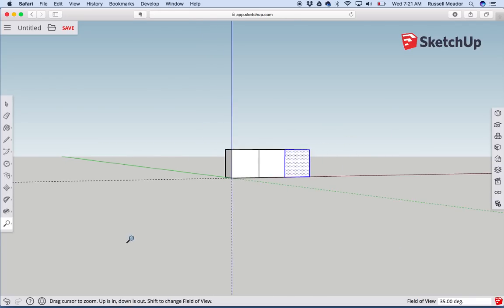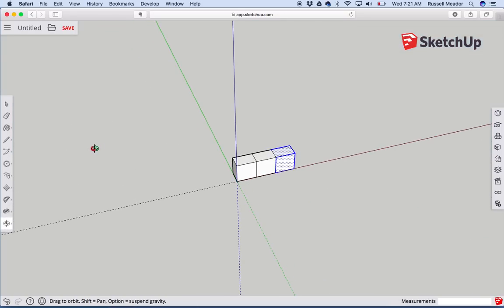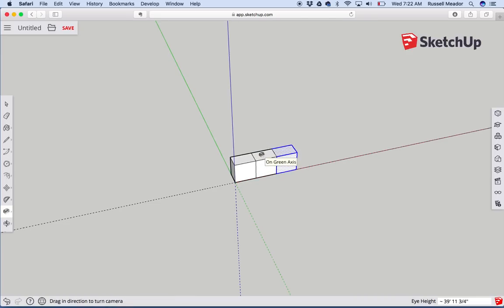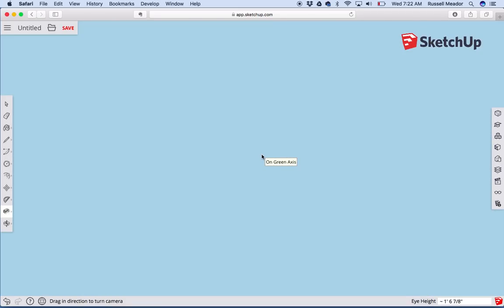Okay. So if we want to do what I call a flyover, let's imagine that you're way up here and you want to slowly, gradually come in and zoom in on a plane. So let's click this guy here, camera position, and let's say that it's right here. And when I release, it's going to do what I call a flyover.